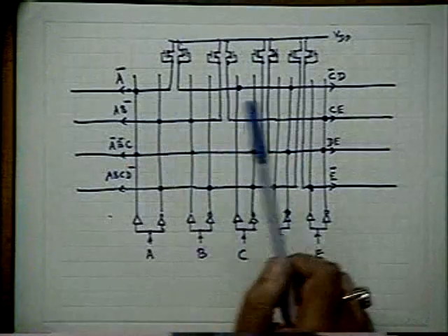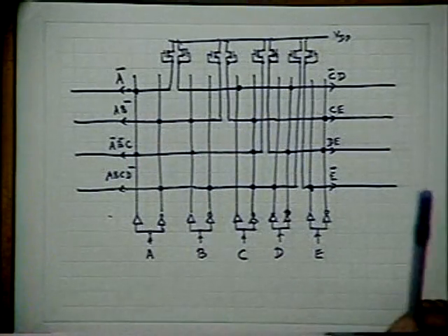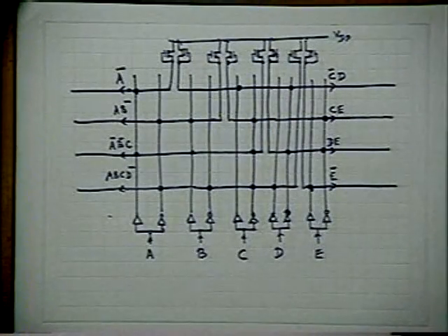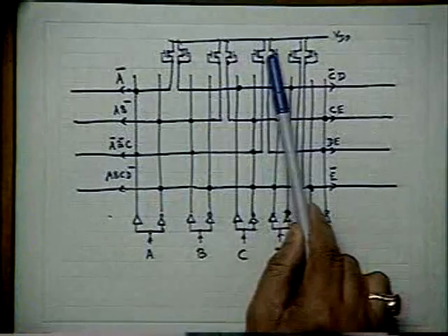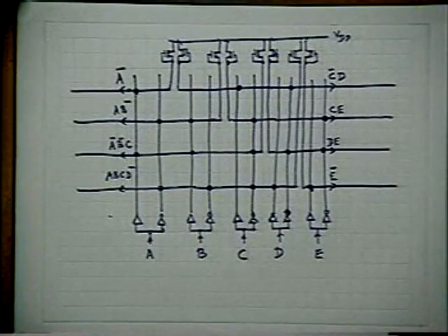They should have a smaller W/L ratio, around 4:1 or 5:1. But with the other kind of configuration, each nMOS would have taken a lot of area. The overall chip area would have been very, very large. Therefore, HMOS technology is most suitable for this kind of nMOS realization, where the load transistors are all, please remember, this is very important, depletion mode MOSFETs. Okay? And this one is done.